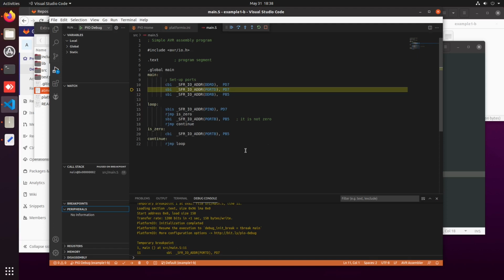So it's interesting, if you have seen the previous videos, that the debug console is actually the console for the GNU debugger. You can write commands here to print and set things and set breakpoints from here. But this is captured by the interface, so we have a nice interface here. These are the debugger controls. We can move it here. From these controls, you can continue the execution, step one instruction and everything. You can restart the simulator, and you can stop the debugging session.